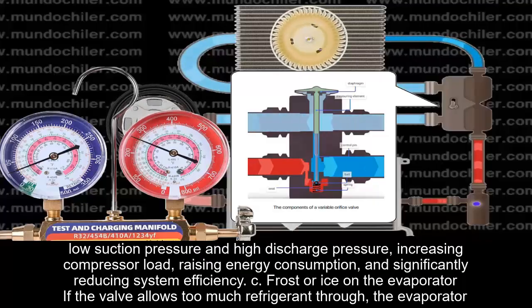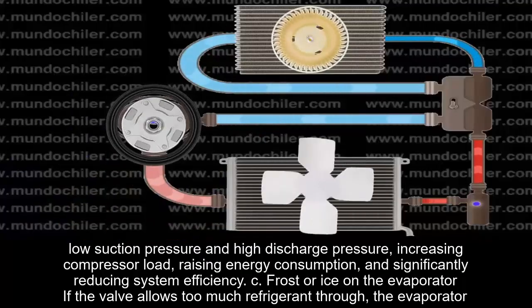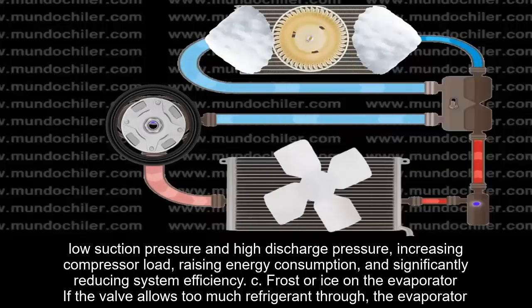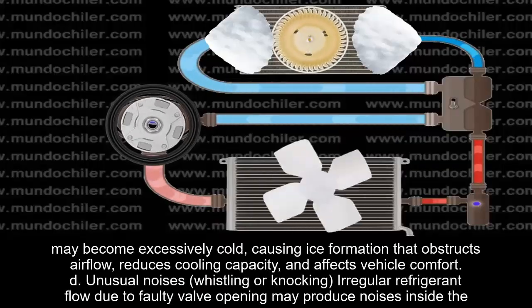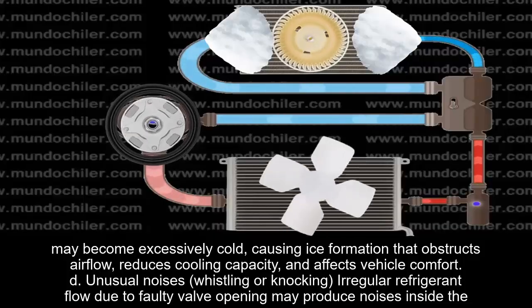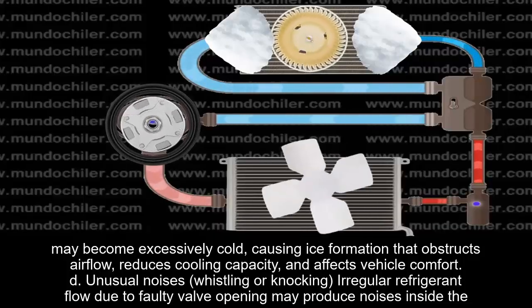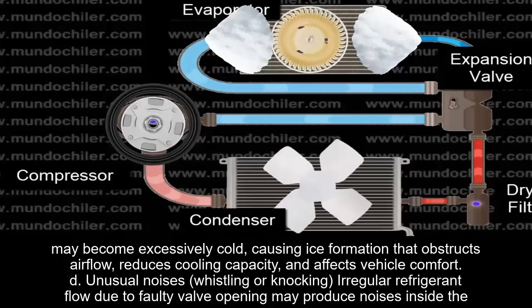C. Frost or ice on the evaporator. If the valve allows too much refrigerant through, the evaporator may become excessively cold, causing ice formation that obstructs airflow, reduces cooling capacity, and affects vehicle comfort.